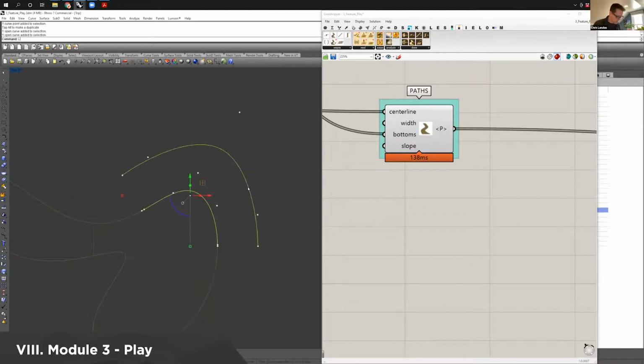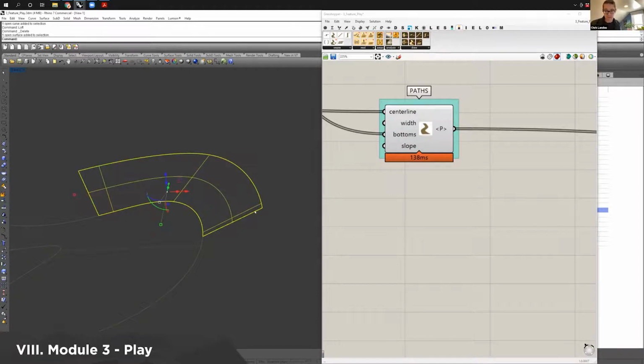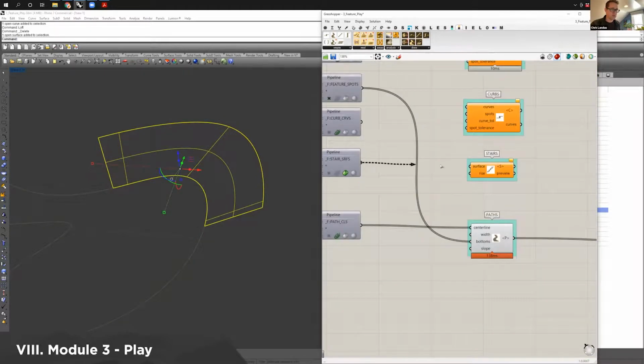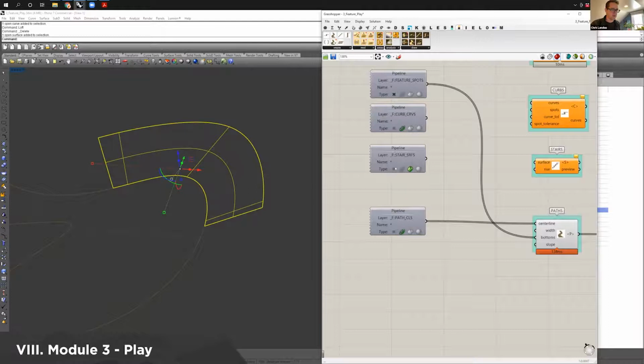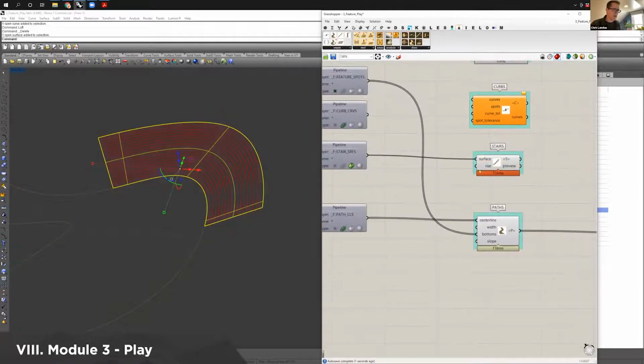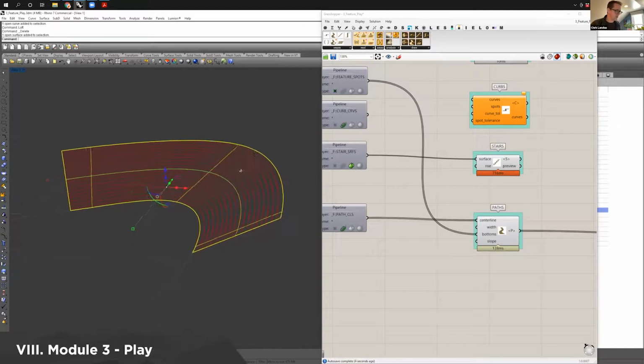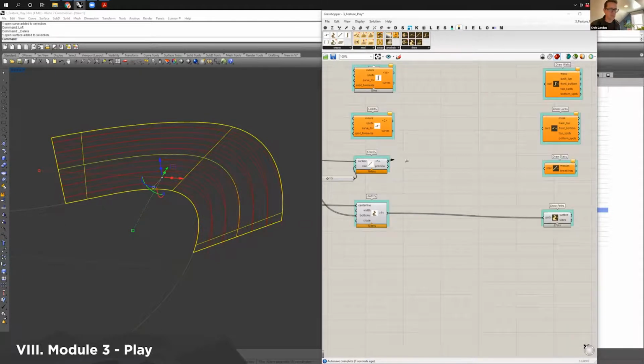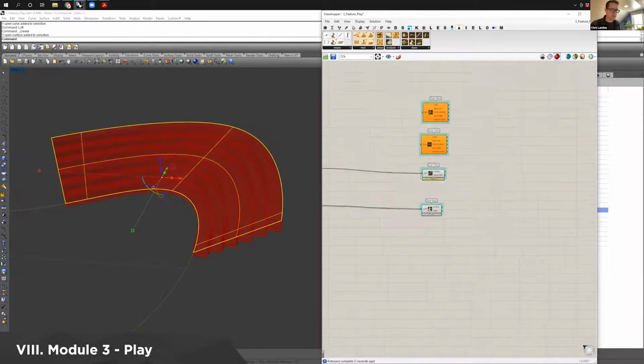And then I'll loft between them, as we said before, and delete the curves, because sometimes I'll put curves like that on some layer, but the curve is there. It's in the stair, right? Then I take that surface, and it's being brought in via the geo pipeline. I can plug it in here. Our rise right now is set to 0.5, but because I'm making this crazy amphitheater, it's 1.5. And then I'll plug this into the draw stair and maybe a preview.